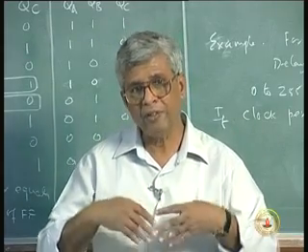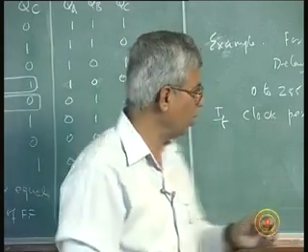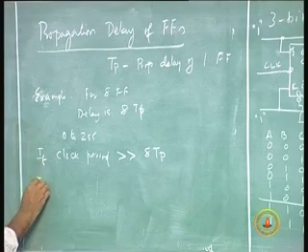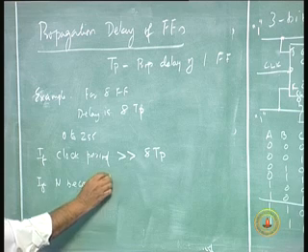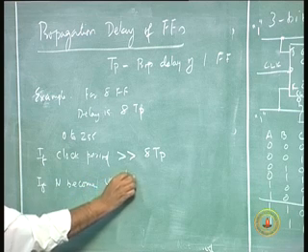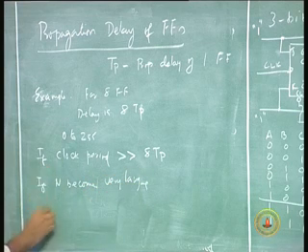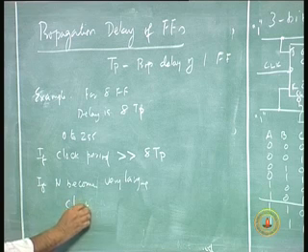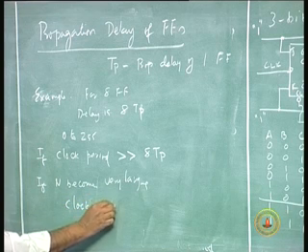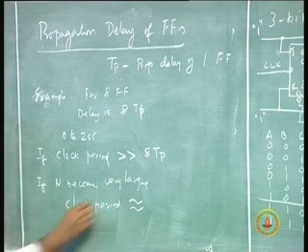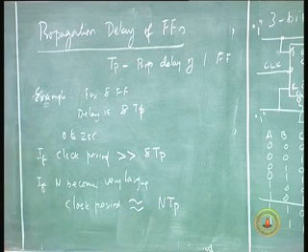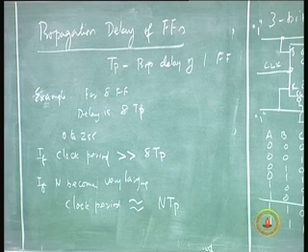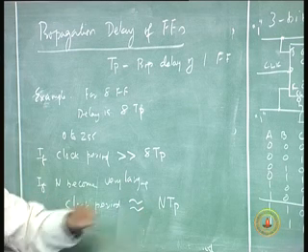But supposing I have a number of stages more, if n becomes large, the clock period may approximate the value of the propagation delays of the n flip flops.